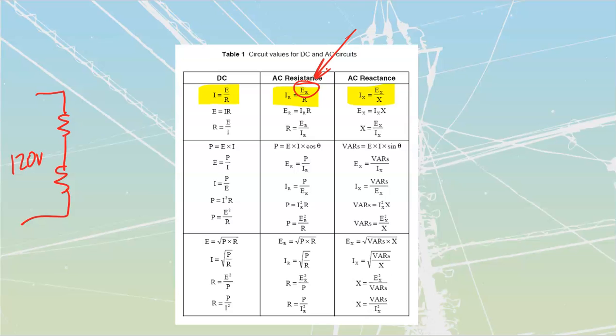So when we're dealing with our resistors, we see this R subscript. What we see in the final column over here, and it's a new column for us, but it's still the same old, is reactance. And it's identified with an X. Now, we have talked about the fact that inductive reactance is identified as being our XL. We are going to find the current through any sort of inductive component the exact same way. Take this and substitute in an inductor.